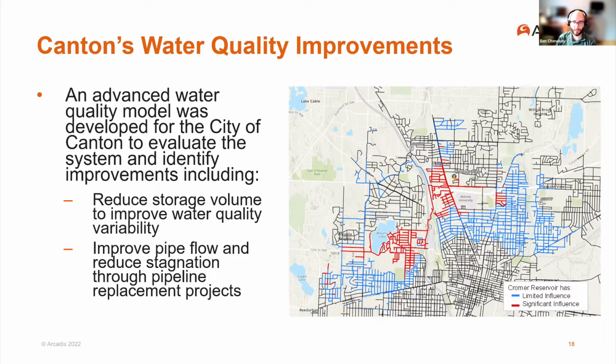influence those areas. And actually that's some of the areas correlated really strongly with those areas that we were seeing those low pressure or low chlorine residual results sometimes in the systems. So it was obviously having some turnover issues and oversize. So we looked at reducing that storage volume and again, understanding what the water age impact was, but also the chlorine residual impact, where they would be able to actually see that out in the system with their chlorine residuals.